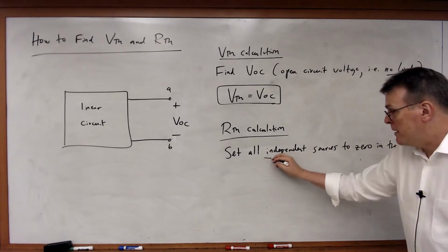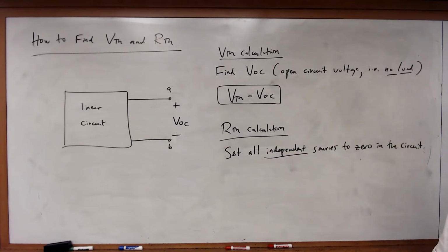Set all independent, not dependent, independent sources in the circuit to 0.